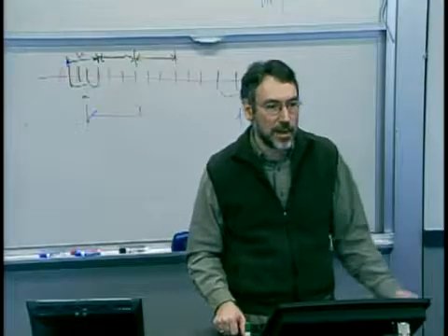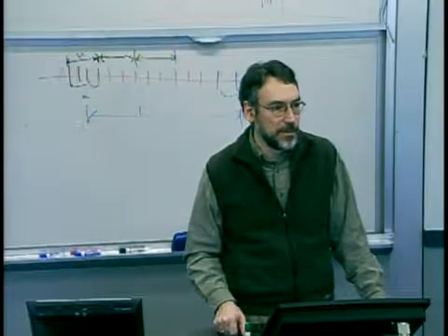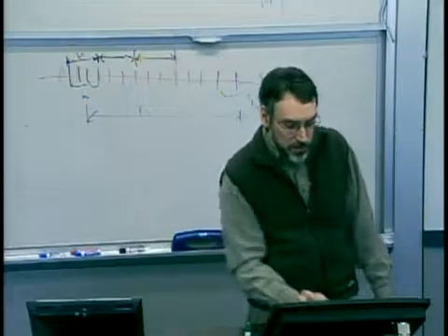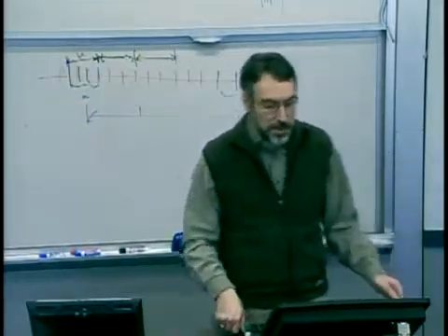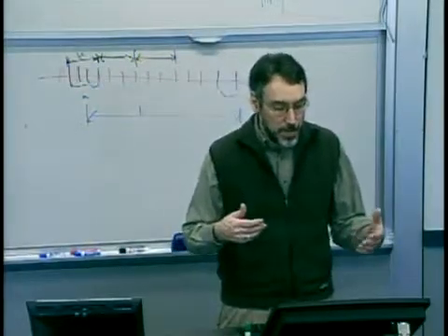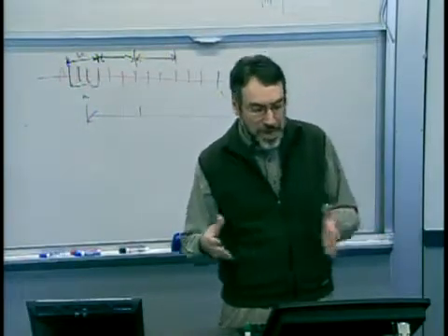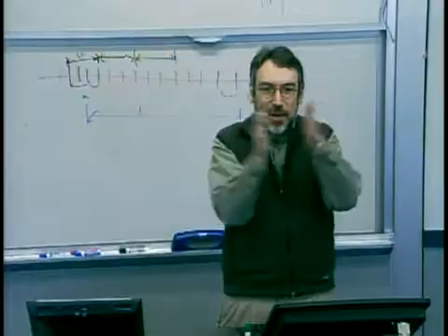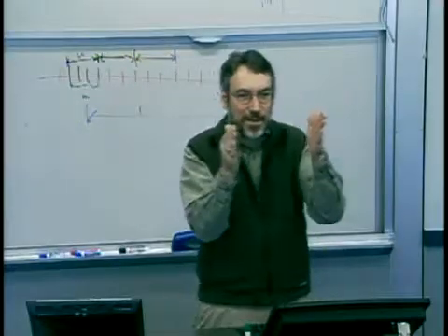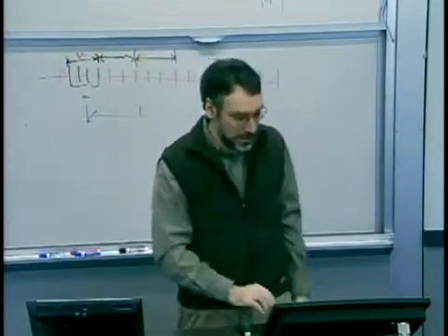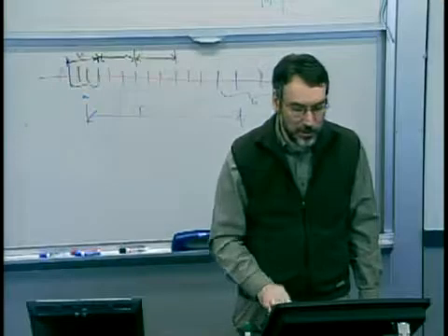You can also ask how my probability of getting non-conforming parts changes as a function of how far off target I am. That's just shifting the distribution and moving those tails around. So you can evaluate both of these.